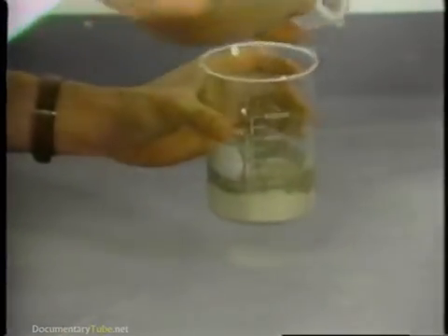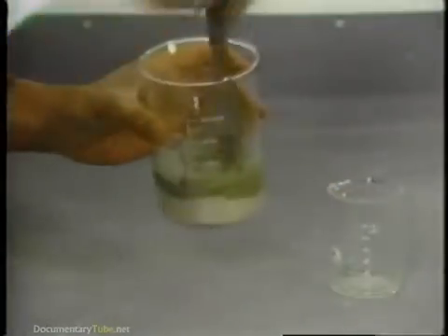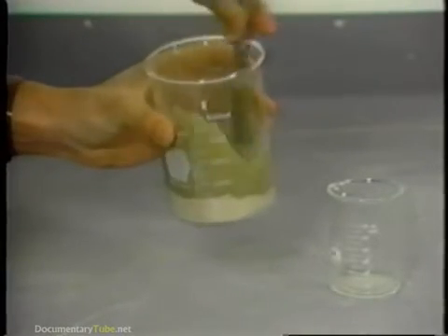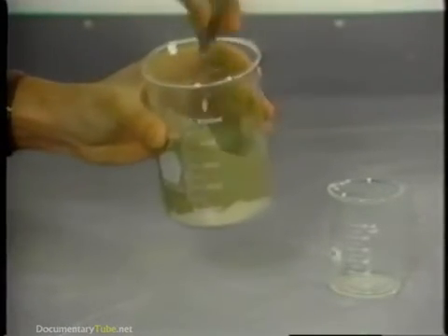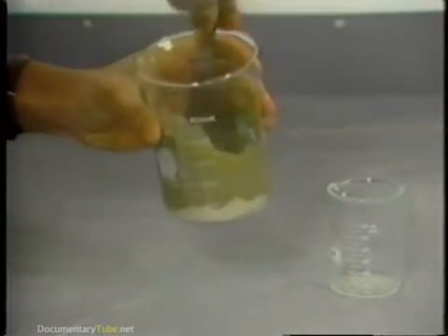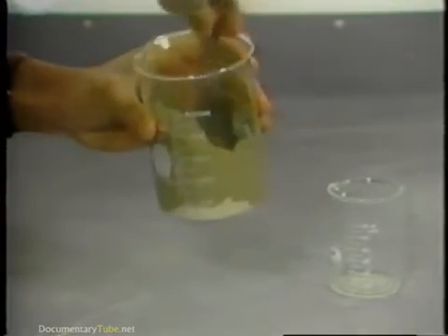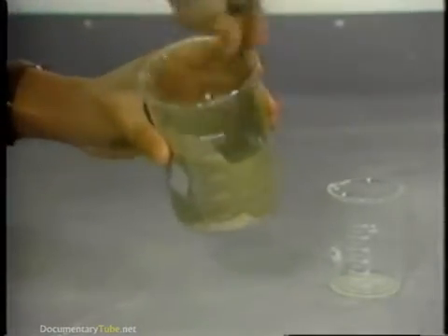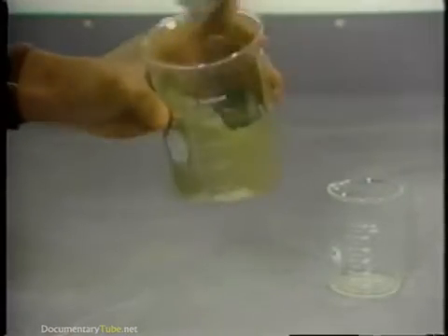The chemical reaction between cement and water is called hydration. The dissolving cement increases the levels of calcium and silicon in the solution. When the concentrations of dissolved species reach critical levels, new solid products are formed through a precipitation reaction.